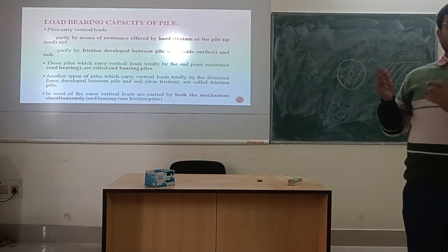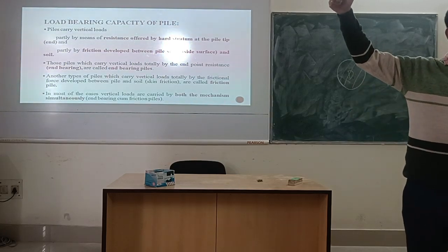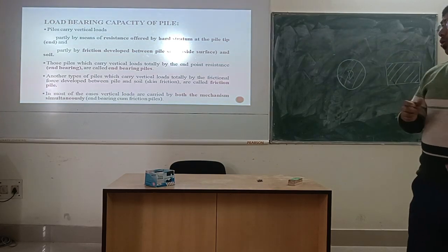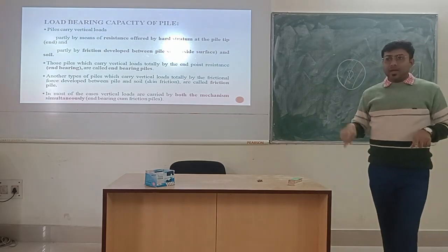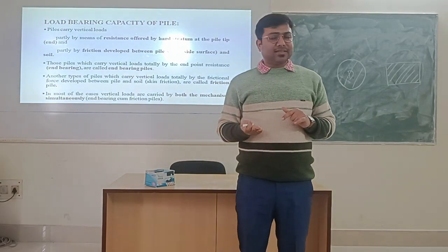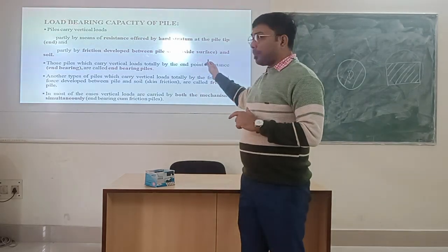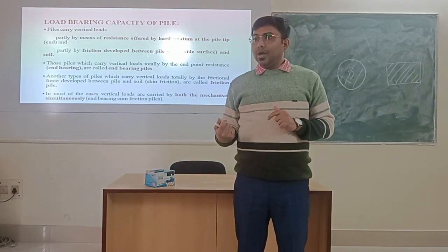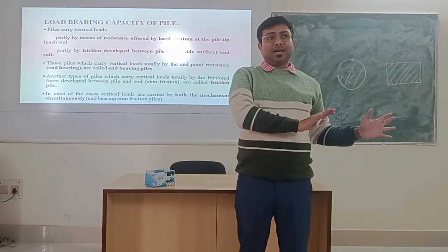Is that okay now? Because there is no friction type of thing, or no shaft, or no length of the footing. Is there any length or friction mechanism in the shallow foundation? No. Only the area of the shallow foundation, whether rectangular footing or square footing or circular footing, the bottom area will take care of the total load. So in the case of pile, the pile tip, the bottom area of the pile, will take care of some amount of the load. So this is a similar mechanism to the shallow foundation or footing.